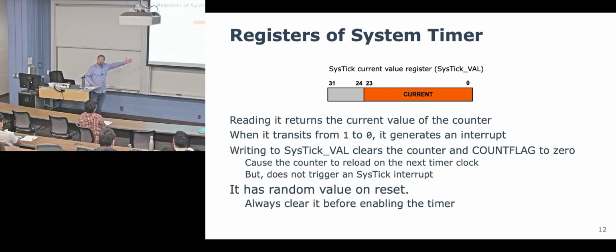We just found the source of random values in here. We find out it's not actually really random. It's random per chip. From one chip to another one, it'll be random. It won't be constant, but it won't have enough variation to be considered truly random. It might be that some bits are a little bit more variable than other ones, but in general, there's a group of numbers that kind of clusters in a way that's not truly random.